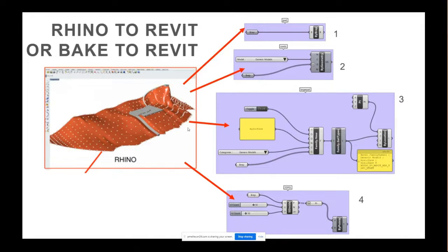It actually takes geometry from Rhino and brings it into the family template. You can assign a family template, maybe a generic model, maybe a structural framing, whatever template you're comfortable with. You can assign it a category. A category could actually be different than the default category of a template, and then you can load that inside of Revit. So it embeds your geometry inside a family.